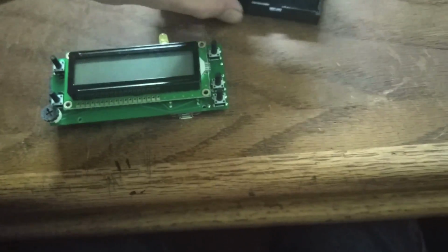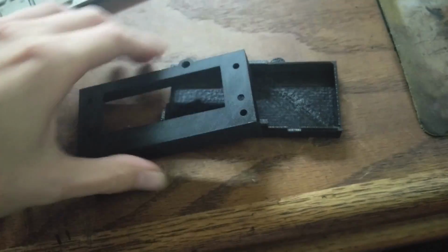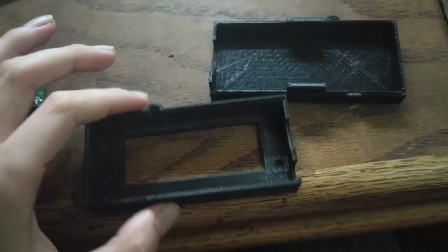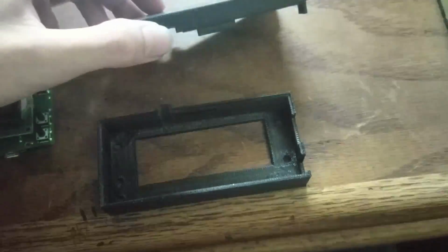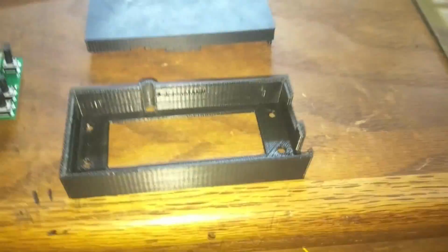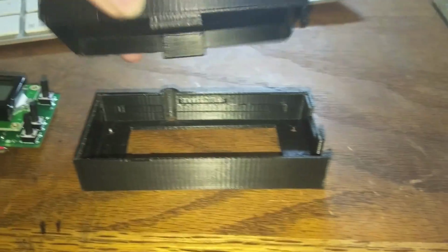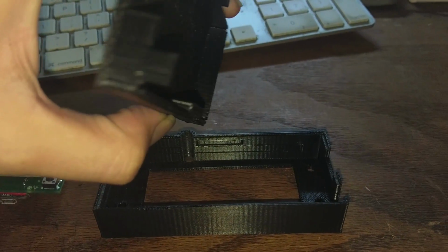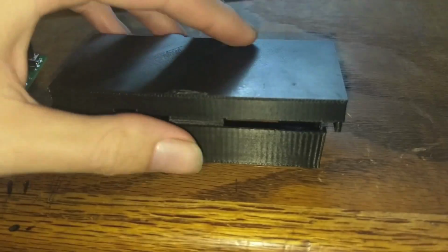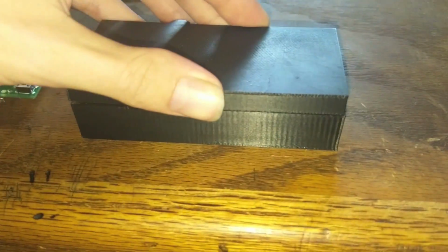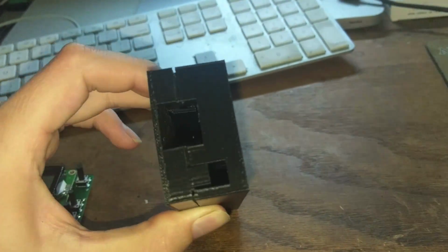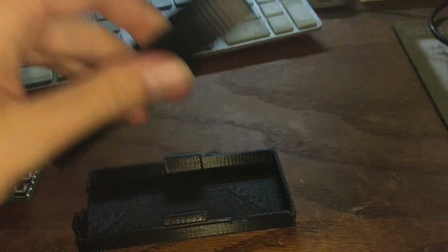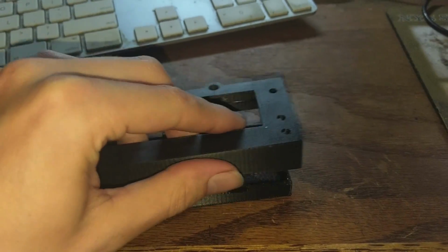The other thing I need to do is finish the case. So here is what I've got going on so far. We got the outer piece, and then a back piece. I'm trying to work on snap fit, because that isn't easy. So we have a little thinger-dinger, and you got a thing, and it snaps into place, but I need locating tabs, and also the snap fit isn't strong enough for how big this case is. It's real easy to pull it apart, and you'd accidentally pull it apart all the time.